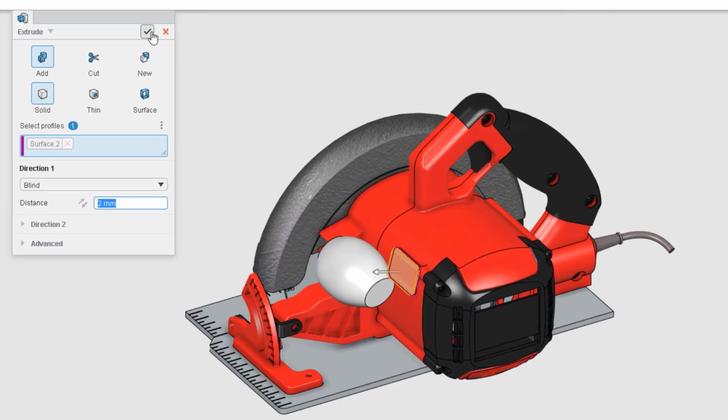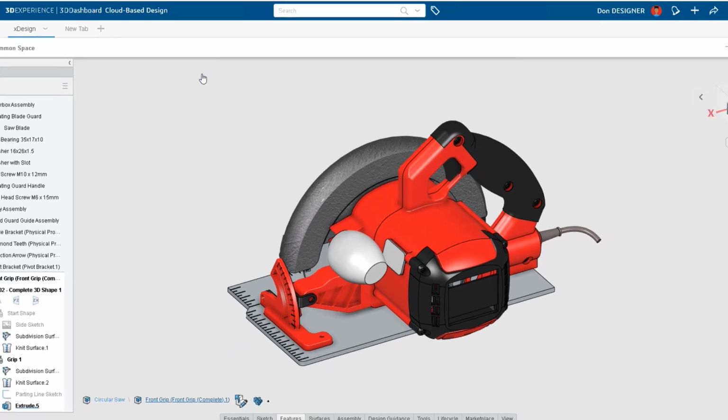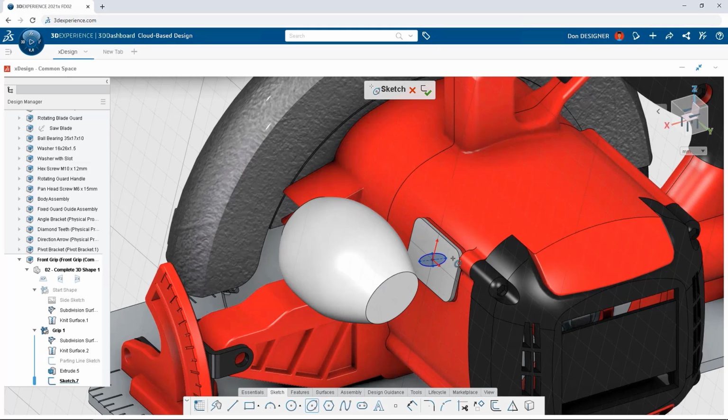So you want to start off with a little base plate to begin with, and this way you'll notice the first nice little enhancement. You can skip the sketch stage and simply select the face and add the option to extrude out. No need for a sketch. Once he's got that done, he then wants to further his design by making use of the ellipse tool. So you can then sketch in his ellipse, and this way we'll see we now have 4 quadrants in here for our ellipse, similar to what we do in SOLIDWORKS. We can then either drag those quadrants round in order to place them, or we can simply add in some relations as we go.